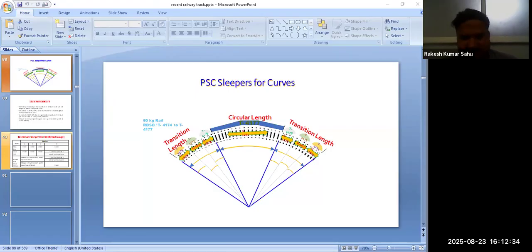Here it is rail free fastening. On the girder bridge, edge beam sleeper, we use rail free fastening. Normally, it only provides lateral stability. Longitudinally, it is free, so it is also called zero resistance fastening system for beam. No resistance on longitudinal movement of rail, only lateral support. It also provides vertical stability to rail and a higher degree of resistance for overturning of rail. No component is left loose in zero load fastening system.